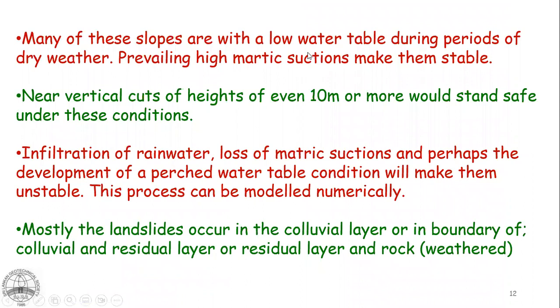Many of these slopes are with a low groundwater table during the periods of dry weather. Prevailing high matric suction makes them stable. Near vertical cuts of height even 10 meters or more would remain safe under these conditions.